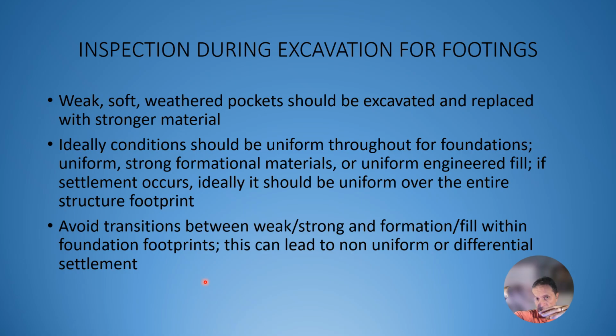So you're going to have to excavate the back half of formation down a few feet so that you can replace the whole pad bearing surface with a uniform compacted fill. And it eliminates the cut, fill, transition, and change in material.